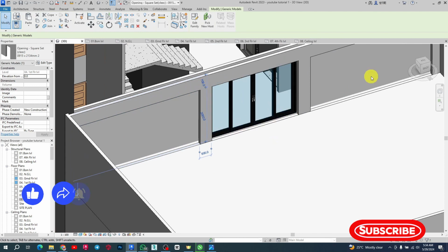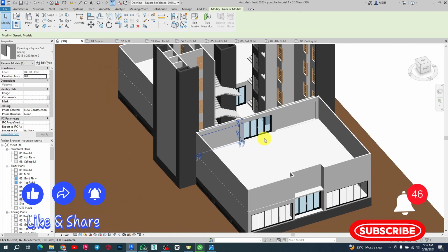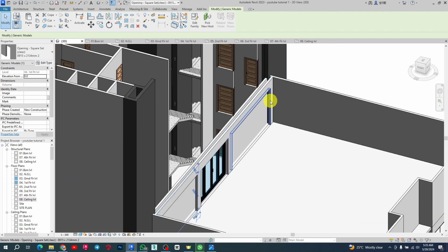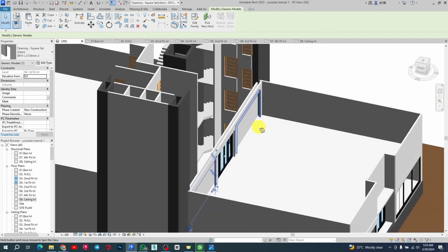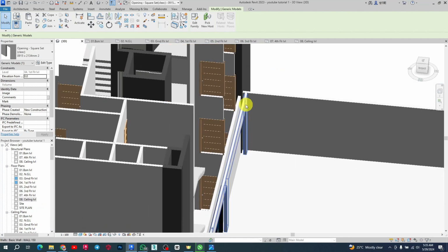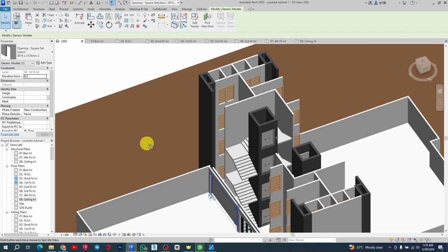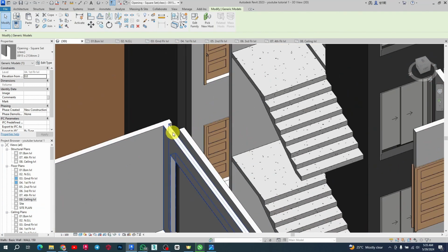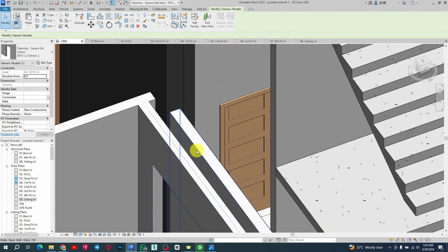So these ones here are actually acting now as if it's a column position, because this will be embedded in the column. So this is a column position and this is an expansion joint, right? So it's the expansion joint, and it has to be 250. The thickness here will be 250. That's why you're seeing the gap too big now. For now it's 150 because it's just wall position. When we add our beam of 250 width, you're going to see it really functional, right?